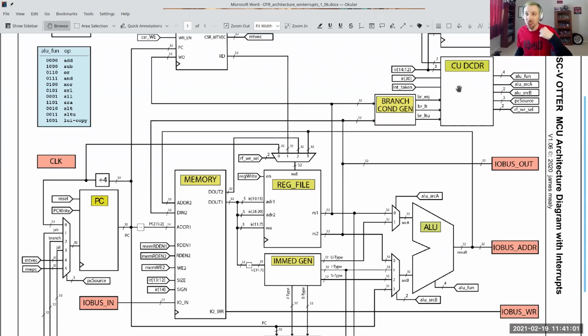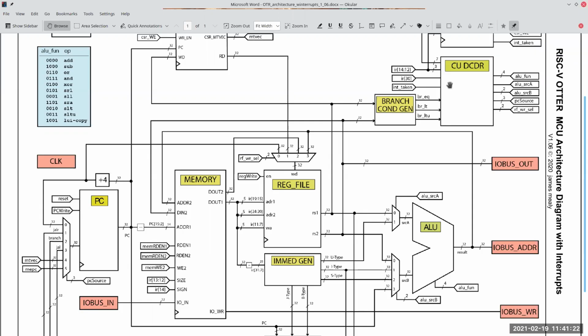Some of you, if you look at your elaborate designs, you see long chains of muxes. Right? So if you have a long chain of muxes, then your path has to go through each one of them. And each one of them adds a little bit of delay. So it'd be things like if we had too many case statements or if statements and stuff like that. Possibly, those would, right?